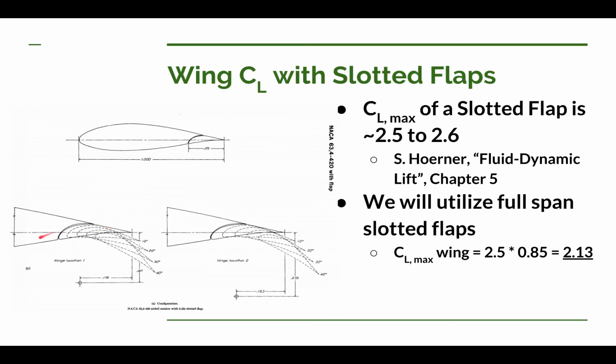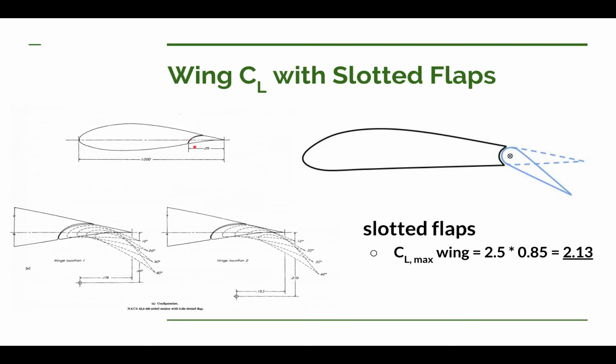This effectively gives our wing much greater camber, so this increases the lift of the wing without significantly increasing the drag, at least compared to plane flaps. Think a little bit about how plane flaps work. You've got a semicircle up here where the nose of your flap is, and that nose stays in the same position, at least around the hinge line right here, and then the trailing edge flops down. So what you're going to have then is a fairly abrupt change in this surface area here when you start dropping this trailing edge down, and you're going to get separation and thus a significant amount of drag, particularly as you increase the angle of deflection.